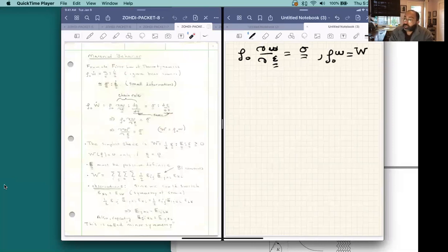This is sometimes called the strain energy, and you might have seen this as undergraduates. That is the energy, for example, that's stored up by springs, that's stored up by elastic bodies, but it is the energy normalized by the unit volume. So this is per unit volume, and this is per unit mass, the little w. We like the per unit volume. There's a number of reasons that over the years this has been the preferred measure, although we could probably rewrite everything in terms of this, but it's a little bit easier to simply absorb the density in the definition and just have a single symbol.